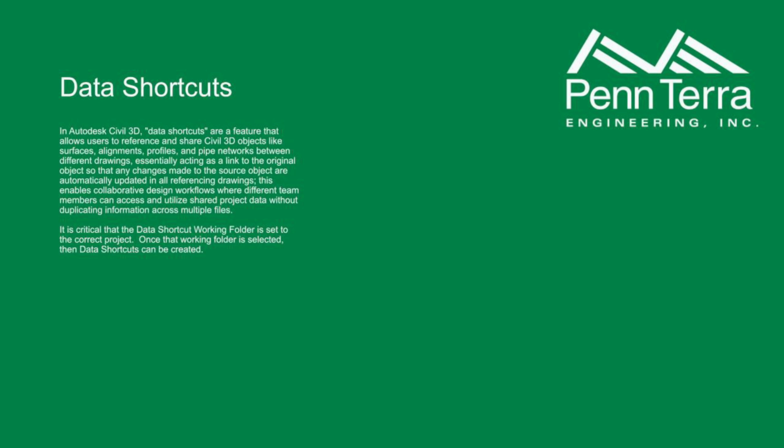Data shortcuts. This one is definitely important. We could cover this in its own topic by itself. I just want to reiterate what is a data shortcut. It allows us to take any of the Civil 3D entities that we have and share them with other people. It's very similar to the survey database that we use.